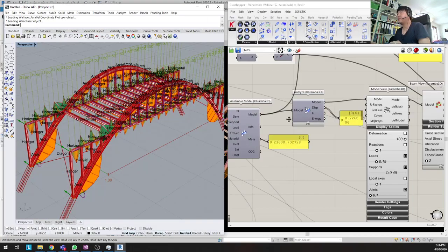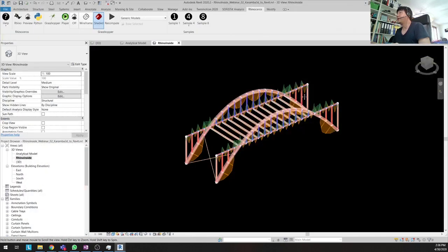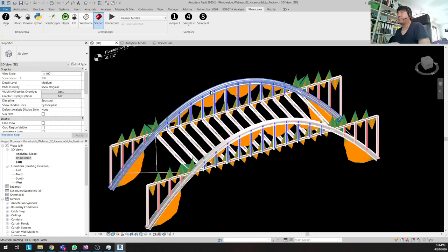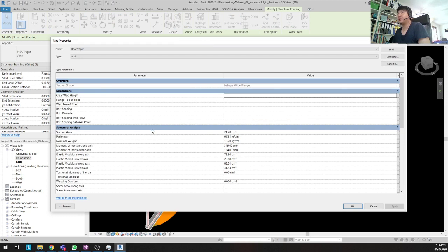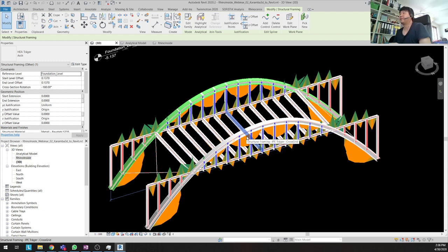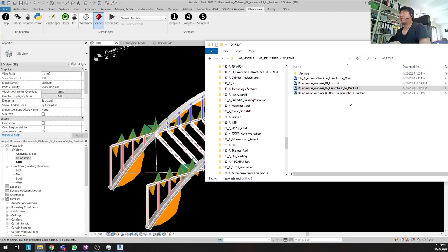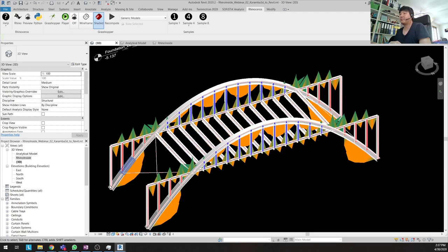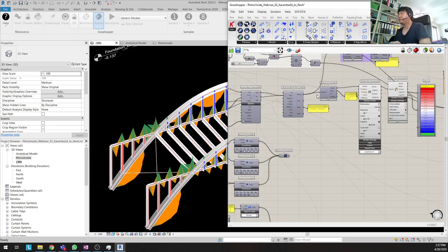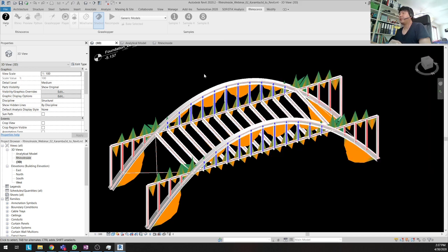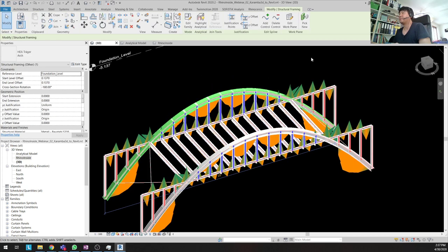So in this example, I prepared all the cross sections based on Karamba input. I manually create the members in Revit. As you can see, I had to load it, but with some plugins, we could automatically generate the members. Or another option we could use is we could generate a type catalog CSV file based on Karamba's definition. This text file allows us to bring all the cross-section members which we used in Karamba automatically.